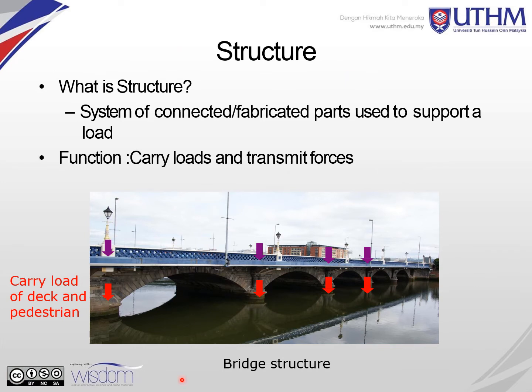Okay, so what is a structure? A structure is a system of connected fabricated parts used to support a load, and the function is to carry the load and transmit forces. You can see this is a bridge structure, where it's used to carry the load of the deck and pedestrians, and then it will carry the loads towards the supports here and then to the foundation at the bottom.